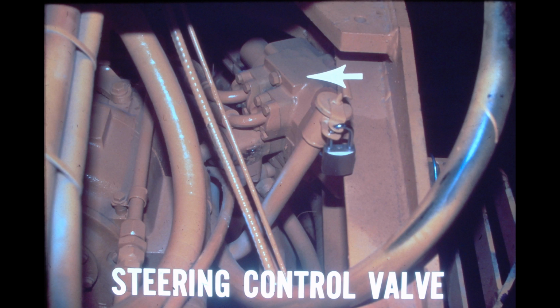The steering control valve is located on the right side of the rear frame, just below the operator's compartment. The function of the valve is to direct oil flow to and from the steering cylinders, which turns the machine. To turn the machine to the right, the spool is pulled out of the valve. As the machine turns, the linkage will push the spool back into the neutral position. The linkage will also return the spool to the neutral position when making a left turn.